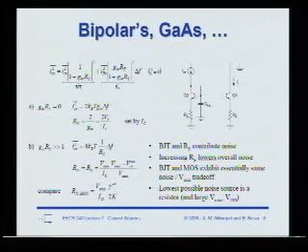Now, typically, when you design a bipolar current mirror, you use resistors. Why do I use resistors here? Because the VBE changes are exponential, so you don't want huge changes from VBE mismatches, so you want to stabilize that. Exactly. It's partly for mismatch. If you do a mismatch analysis, which could be a good homework problem, you can show that the mismatch of VBE kind of goes away and it becomes more or less an RE mismatch. So if you have good resistor matching, you get good current matching. But also, more importantly, it rejects the noise.